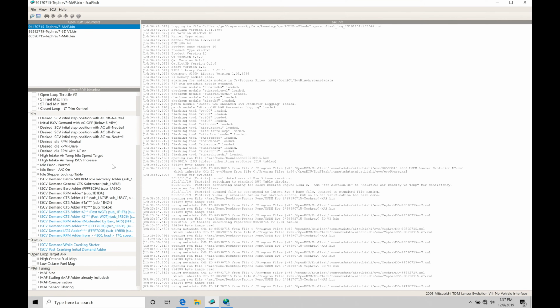So we're essentially going to be programming a virtual vacuum leak through the ECU so we can get the desired results that we like. So again, this is going to be affecting starting, post-start, and our normal idle control and idle routine. So it's very important that we understand which of these tables we actually need to work with and start to program.